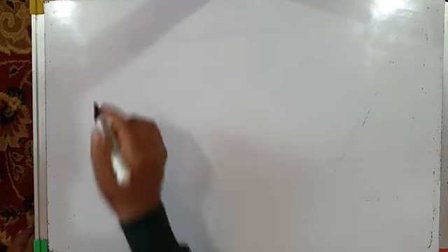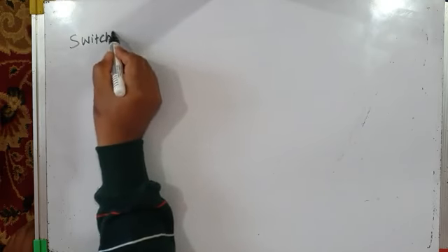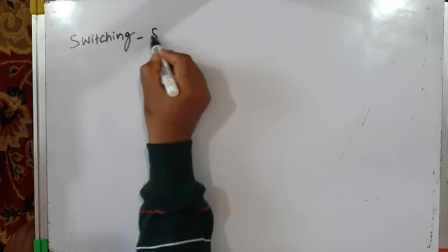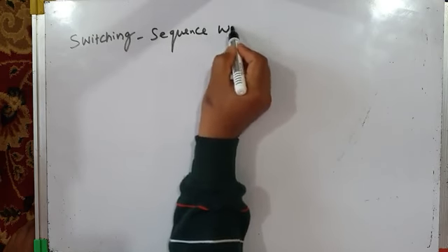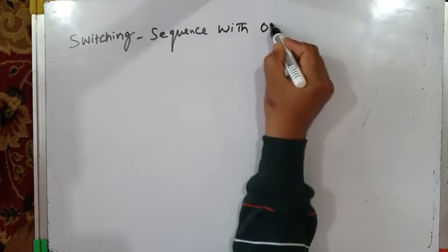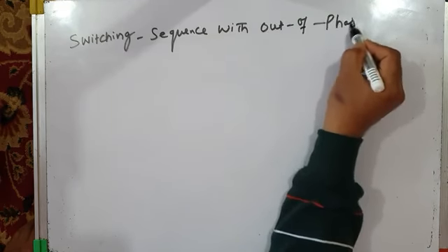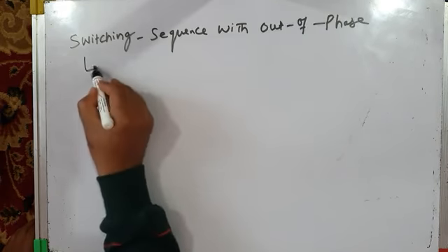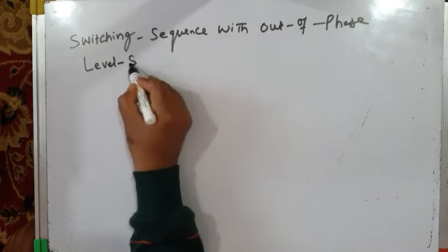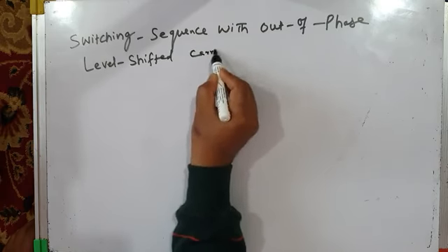Now, it's very important for you to understand the switching sequence. Let us understand the switching sequence with out of phase level shifted carriers.